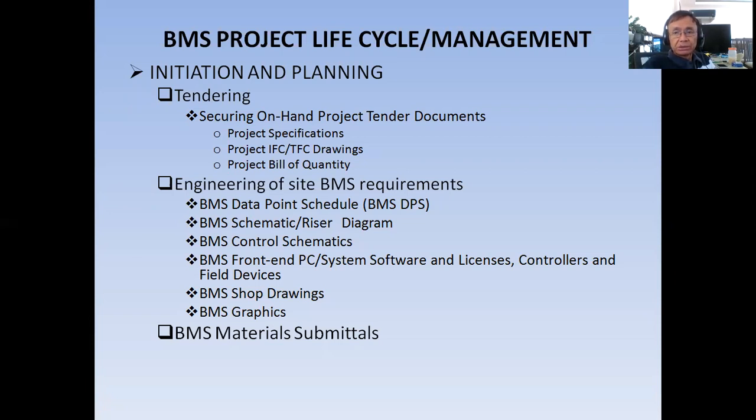The most important here is the BMS schematic riser diagram. You have to convince the consultant how your system software, your server, and your workstation will communicate to all your DDC panels. Okay, so these are the things that you need to do in initiation and planning.